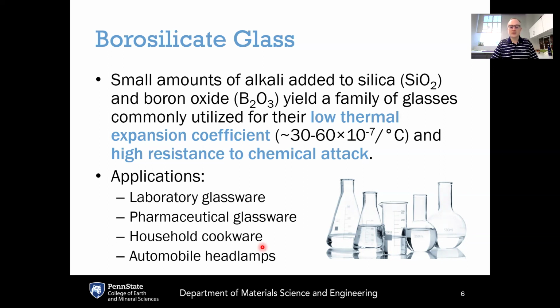That being said, one needs to be very cautious nowadays because more recently, at least here in the US, the company that has been selling glass cookware under the trade name of Pyrex is not actually selling borosilicate glass. They are selling soda lime silicate glass and marketing it as Pyrex. And so as a result, the thermal shock resistance is about 3 times worse. And this has led to several unfortunate accidents with glass bakeware shattering as it comes out. In Europe, there are laws against this, and it must be true borosilicate glass.